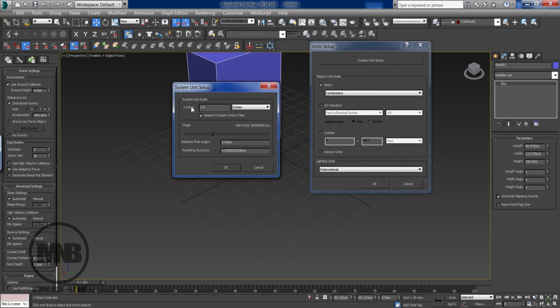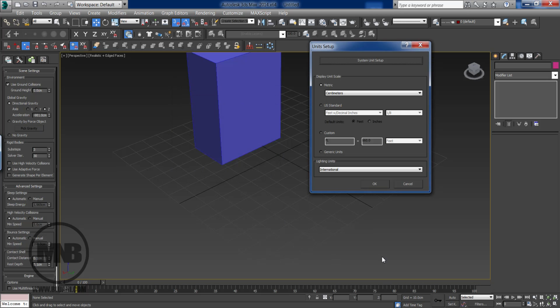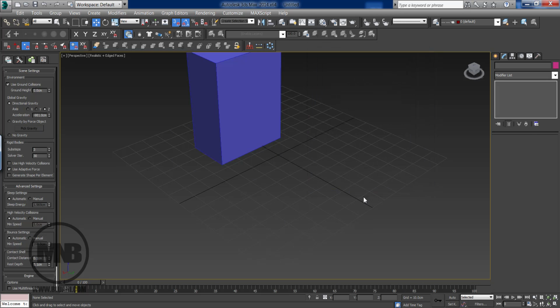And in here, what it's doing is basically converting from centimeters to inches. So just move this into centimeters for my case. It says now grid equals 10 centimeters. If I want to make it 100 centimeters, I just multiply this number by 10, for example 10, so that's going to be 100 centimeters. I think this is good in my case, or maybe 10 centimeters. So I'm going to keep it 10 centimeters, and now it's good.